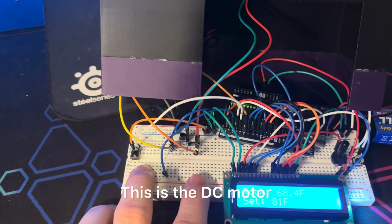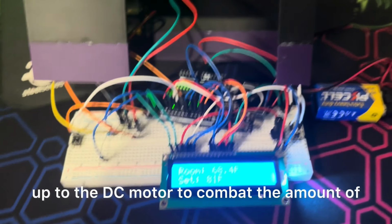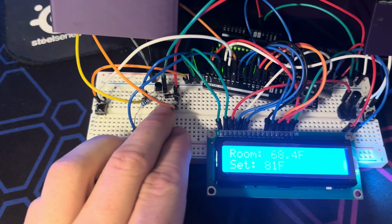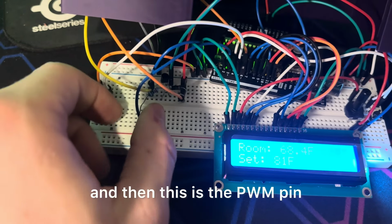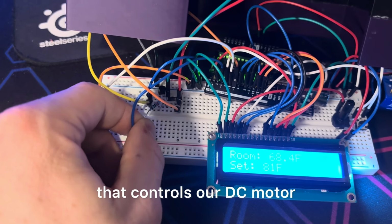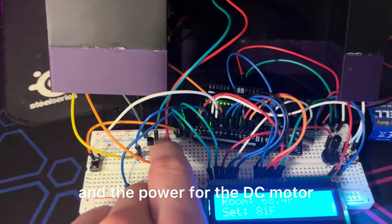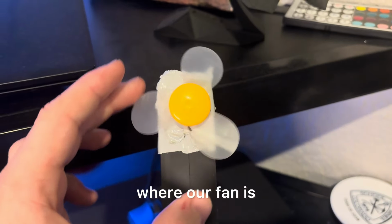The other major area is this here. This is the DC motor. As you can see, we have an alternate power source hooked up to the DC motor to combat the amount of power pulled from the Arduino by the LCD. This alternate power source runs through the diode and a transistor, and then this is the PWM pin that controls our DC motor. These 2 wires back here are the ground and the power for the DC motor. They run up through the container all the way to the top where our fan is.